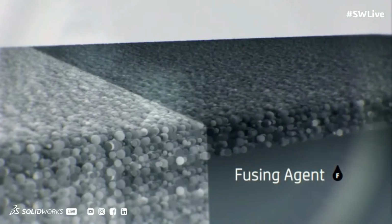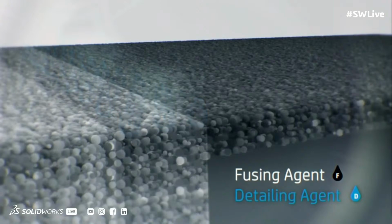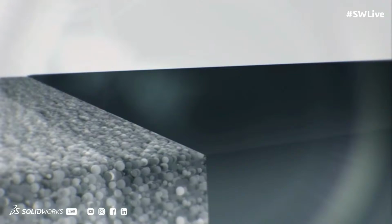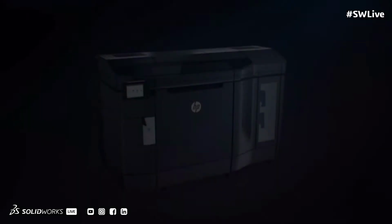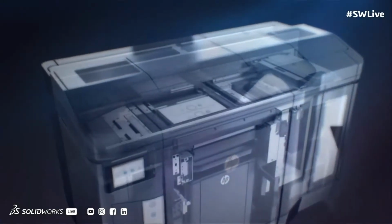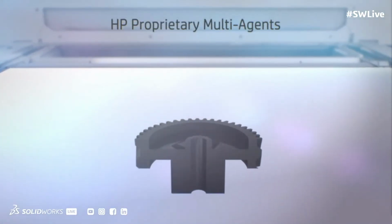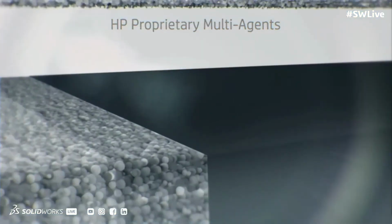So we spread a layer of nylon, which you just saw. Then we spray a black fusing agent onto that white nylon powder, and we spray a detailing agent around the edges to give us a thermal barrier. And then we hit it with high intensity IR light. That light is absorbed by the blackened regions, but it's reflected by the white powder around it. The blackened area goes above the melting temperature of the nylon and it sinters, whereas the white powder around the rest of the part does not get above its melting point. So you can see here, layer by layer, 3,000ths of an inch at a time, we're building these parts.